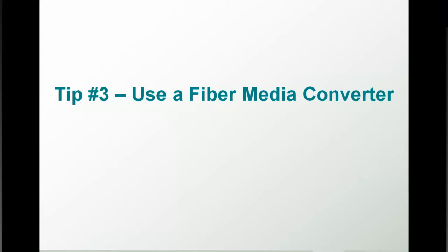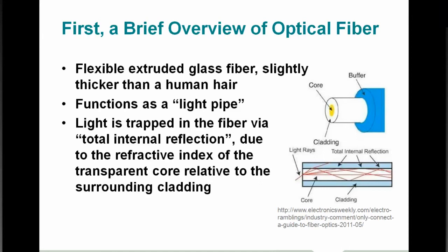Great. Well, fundamentally, you folks know that there's another technology out here called media converters, which allow us to extend those connections. Let's take a closer look at some of the technology driving that. For those of you who aren't familiar with it, the simple concept is taking those electrical signals on copper cable and converting them into short bursts of light carried over a piece of typically glass, but in some very specialized applications, plastic fiber optic cable. For most of what you folks are working with, you're fundamentally working with glass fiber.